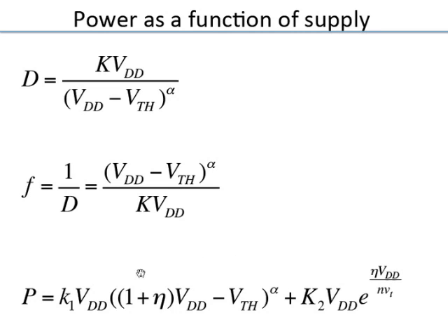Okay. Similarly, out here, again VT. Okay, so I made a mistake here. This VTH is some VTH dash, independent of supply, minus eta times VDD, the DIBL coefficient eta times VDD. So I've just taken that out, and now I have 1 plus eta VDD comes here, and then this should be VTH dash. I should have put that dash, but there's a typo. I'll fix it in the slides.